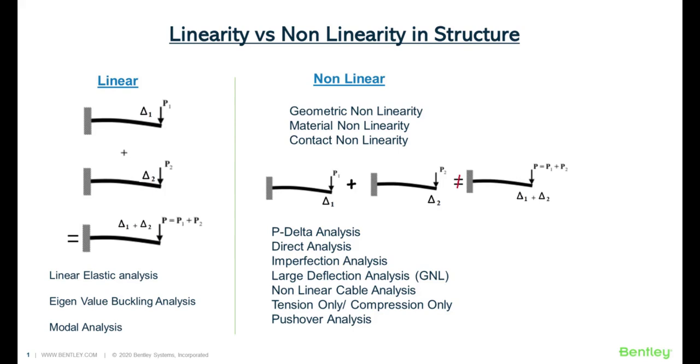Then the program is not going to solve for all the combined effect. It will solve for all the primary load cases, and then it will algebraically sum up the response of those primary loading actions, multiply them with some factor, consider whatever sign you have used, and deliver you the final response. That means the program is just using the post-processing values of the primary load cases. It is not going to solve for the combined effect.